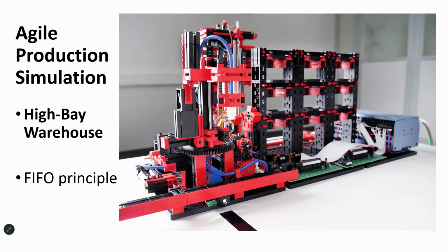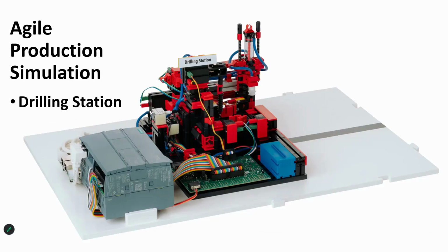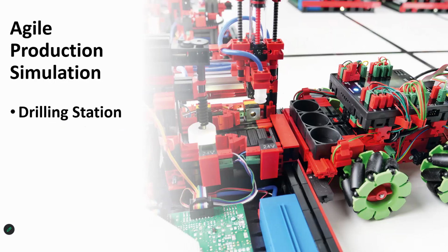The next module that a workpiece could go to is going to be the drilling station. The drilling station consists of a docking station for the AGV. Actually, each of these stations will have a docking station where the AGV, again, carrying the workpiece, docks. Typically, the vacuum gripper in each of these stations picks up the workpiece from the back of the AGV, puts it onto a little conveyor belt here, where it is transported